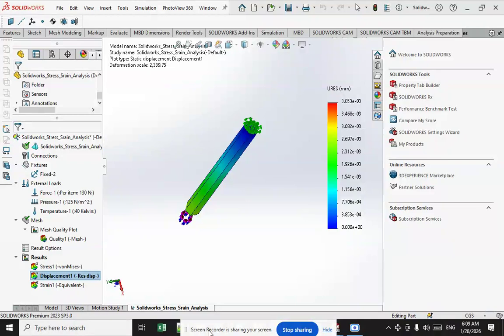The relationship between true strain and engineering strain is given by epsilon_t equal to the logarithm of 1 plus epsilon_e to the base of e. In uniaxial tension, true stress is then greater than nominal stress. The converse holds in compression.